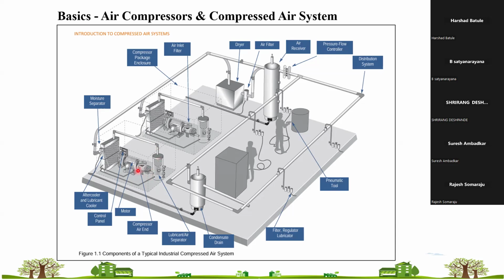After starting the compressor, you need to record the time. You start the stopwatch while starting the compressor. After 4 to 5 seconds your load cycle starts, and the compressor actually starts to deliver compressed air to the receiver.